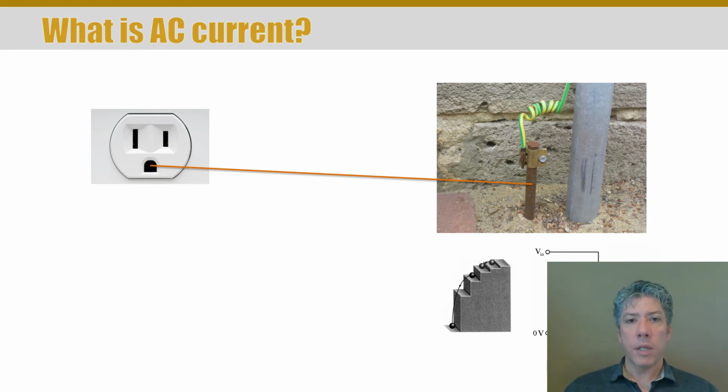Because energy has been lost from the charges as they fall to a lower voltage or to a lower electric potential at V out. And then that's not as far as they can fall. That's like halfway down the staircase, right? If both resistors are equal to each other, they can fall all the way down to ground potential. So hopefully that helps you understand a little bit more about things that you've probably studied in the past. So we're going to define ground as our 0 volts.